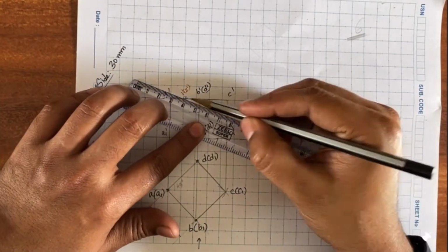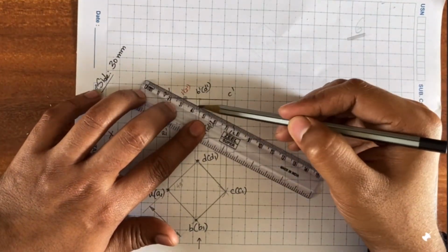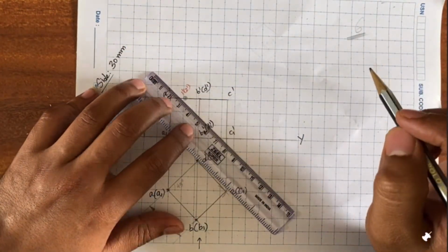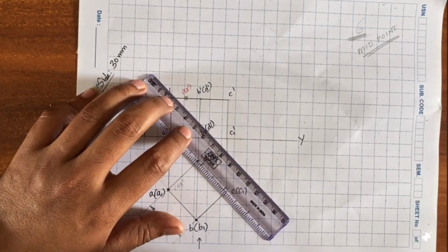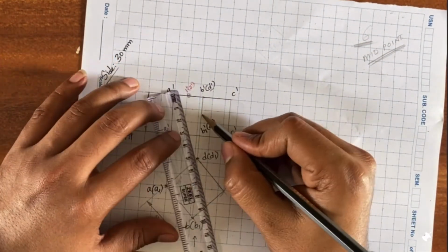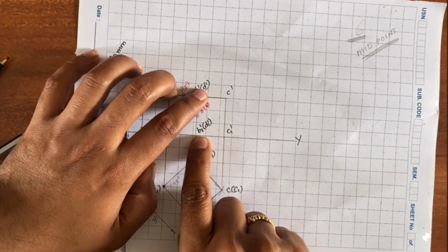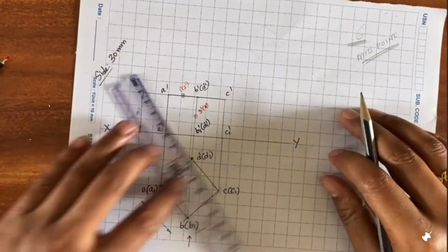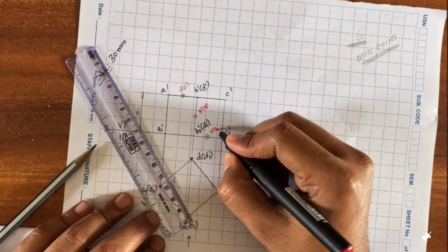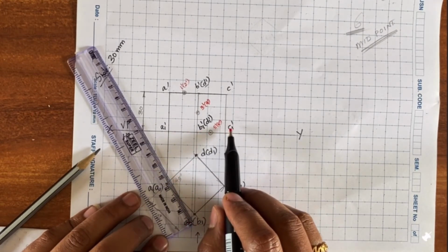So if we cut like this, we are going to get 2 plus 2 plus 1. So totally we'll get 5 cut points, but still we are not able to get 6. So we need to get the midpoint of 6 edges so that we get the 6 cut points. So we'll locate the second midpoint over here vertically, where we'll mark it as 3 dash 4 dash, and inclining it to the bottom base midpoint of B1 dash C1 dash and C1 dash D1 dash, we'll get another 2 points, 5 dash and 6 dash.